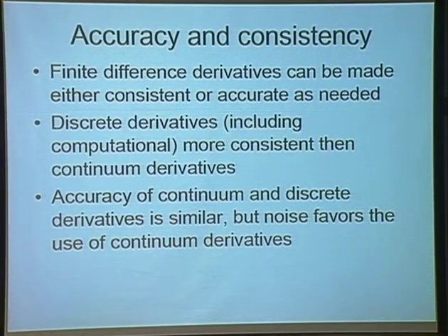If you call fmincon without telling it that you are going to give it a subroutine with the derivative of the constraint, it will go ahead and calculate it by finite differences. And if that's affordable, then you sort of forget about derivative calculation.